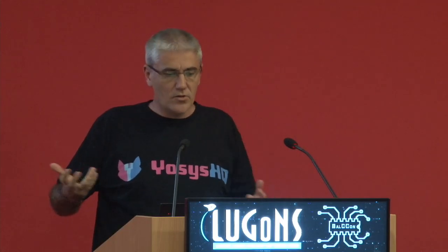As I mentioned, you have a CPE that basically consists of the LUT trees, but in your design you would just have some expressions. Those expressions will be converted by Yosys to a set of such primitives, and then we can pack, for example, two of those LUT trees into one CPE.